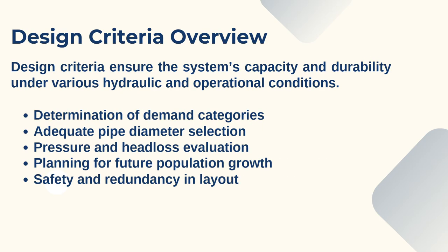Next is the design criteria overview. The design criteria ensure the system capacity and durability under various hydraulic and also operational conditions. These include determination of demand categories, adequate pipe diameter selection, pressure and head loss evaluation, planning for future population growth, and also safety and redundancy in layout.